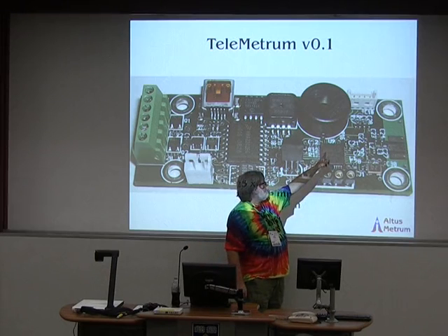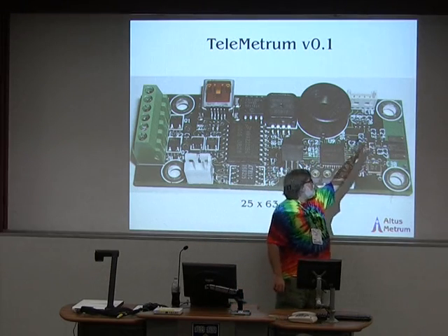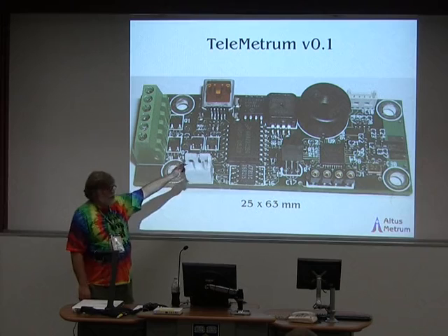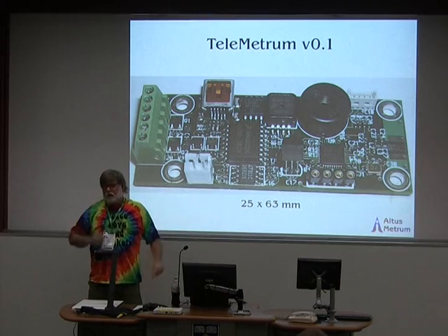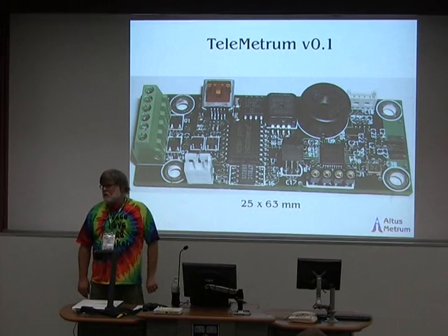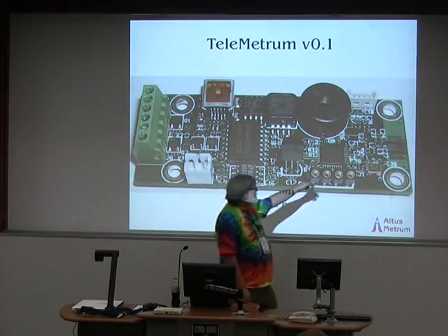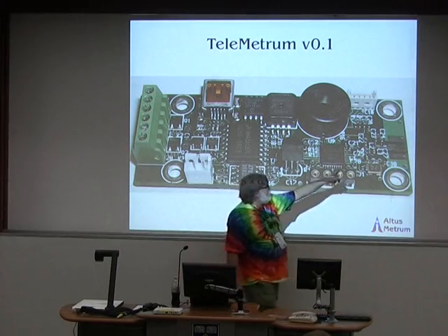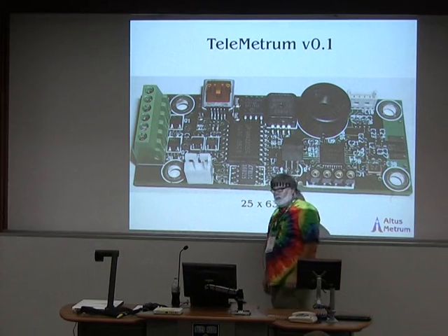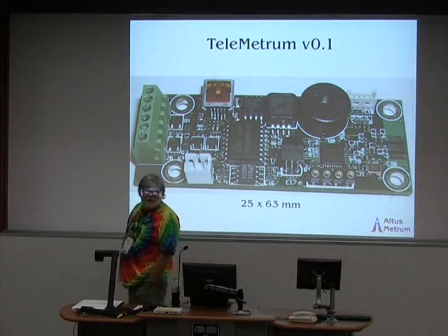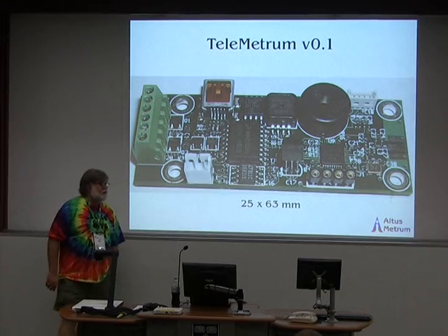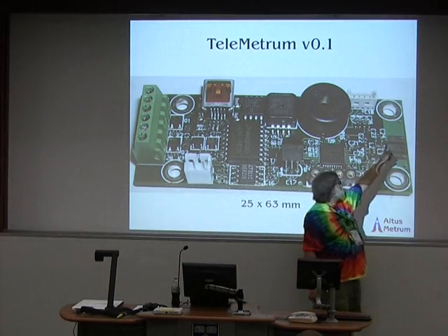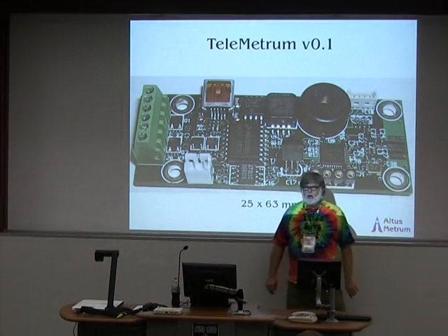But just to point it out, this is the interesting part. That's the CC1111 right there. And this part over here is the UHF balun and filter assembly to basically take the differential output and input interface on that transceiver chip and bring it out to a single-ended antenna connection at 50 ohms over here. That footprint on the end of the board was designed so that an edge-launched SMA connector could be soldered on. But I really have only ever used those in a couple of odd circumstances and for bench testing. Almost always what we end up doing is soldering a wire whip to that center pin and just letting it stick out into the airframe.